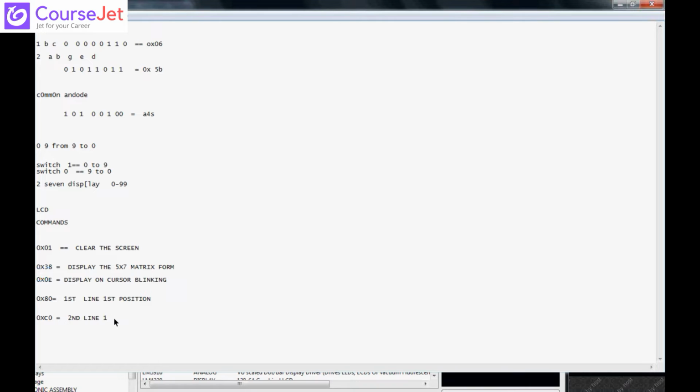So at that time I can't have C0 or 90 as the address for second line. So to not get confused every time, we have second line address as C0 with first position. So here the address will be from C0 to CF, as it is for 16. You got my point here? If you have 32, 17th position will have the position address of 90.